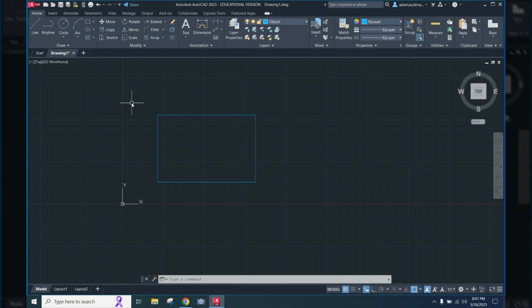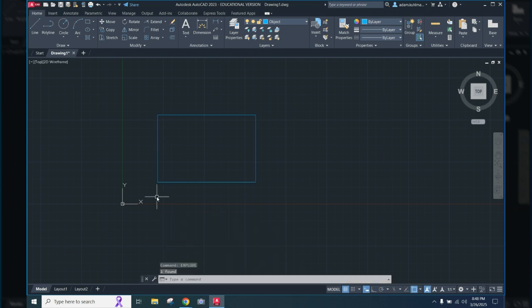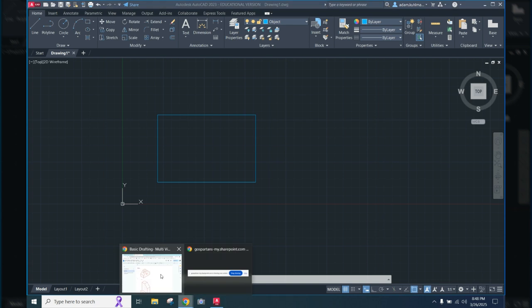So to make my life a little bit easier, I'm going to take my rectangle and come down here to the command center and type in the word explode. Some of you may have used the text explode when you made your house numbers. What explode does is it makes this into 4 separate line segments. Right? So now I can take these line segments and offset them individually versus offsetting all 4 sides of my rectangle all the time. And so this is going to be where my front view fits. Let's go look at that example drawing.